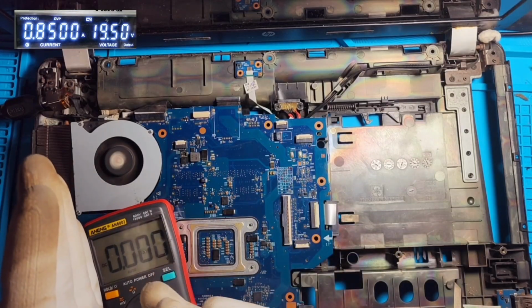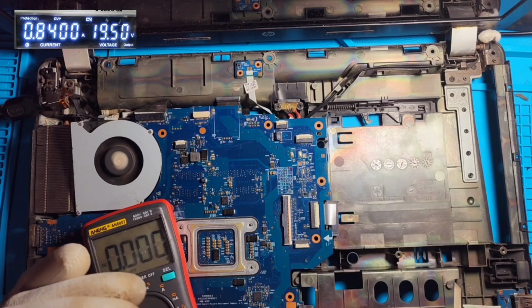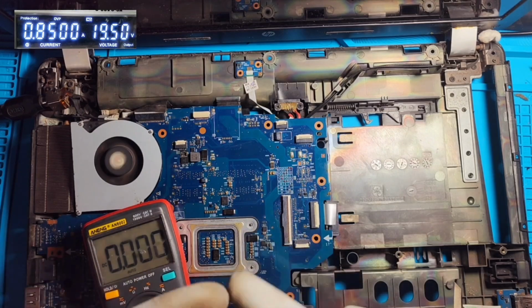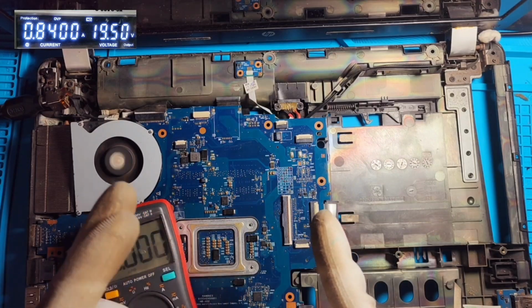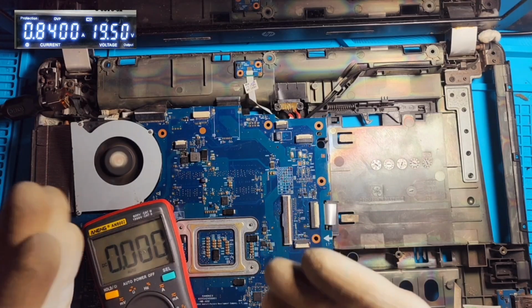So first the diode check and then back with the oscilloscope reading on each of the coils, and then we can move on to the signal testing on this motherboard, so that we can find whether we can solve the problem.